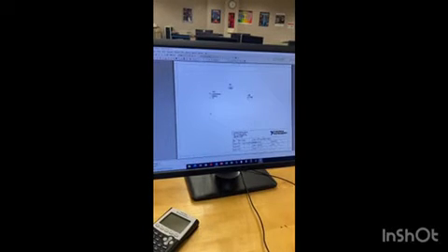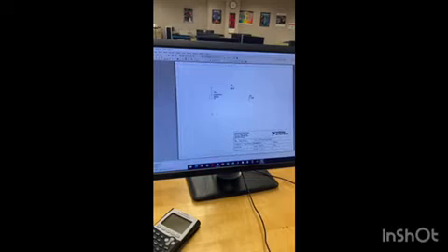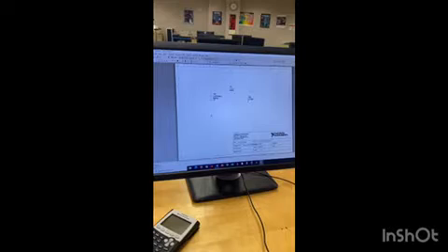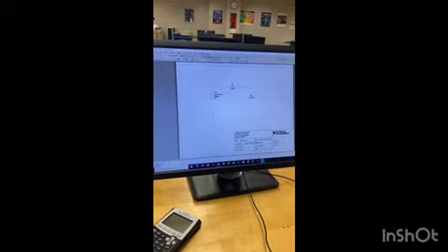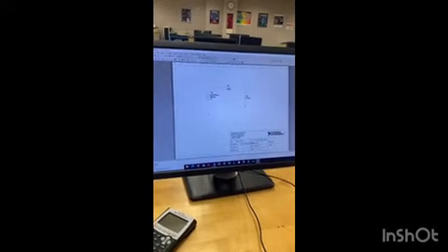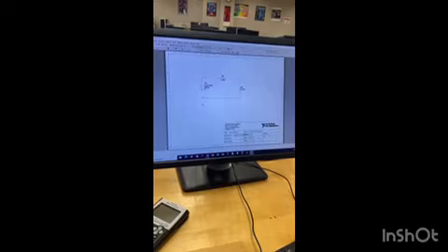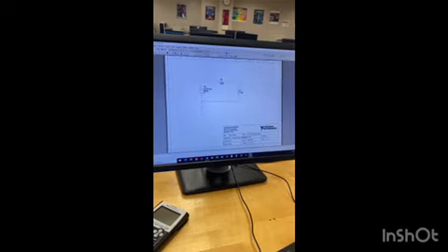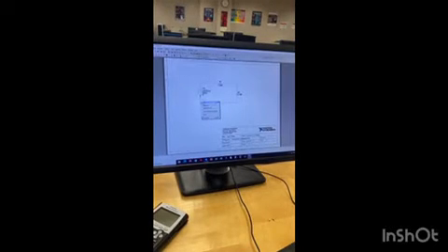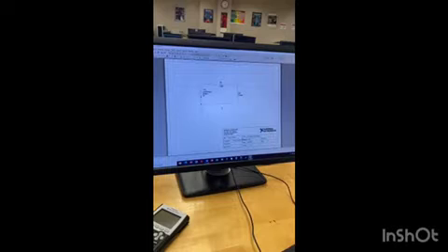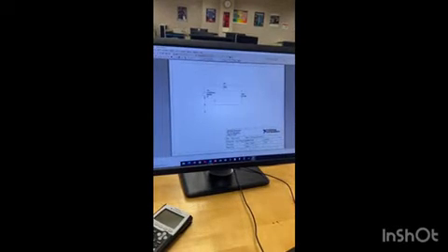Now, we're going to connect our power source to our first resistor, then our first resistor to our second resistor, our second resistor back to our power source, and then we'll finally connect our ground to our circuit. Now we're going to change the net color of the negative end of our circuit to differentiate the power, the positive and the negative.